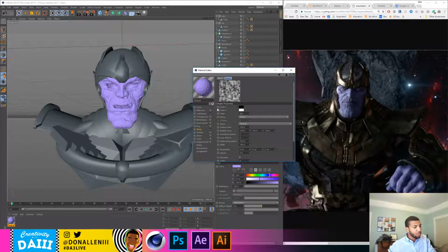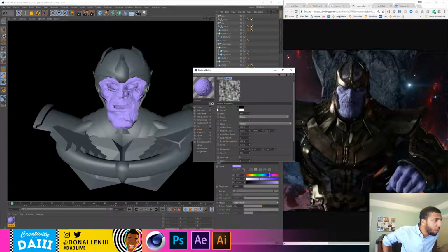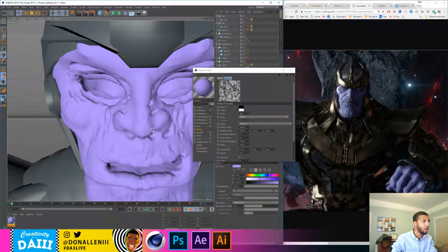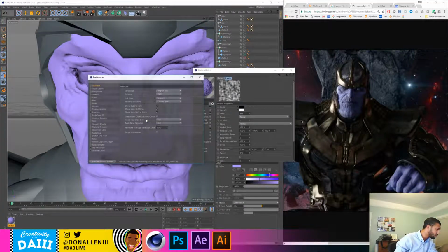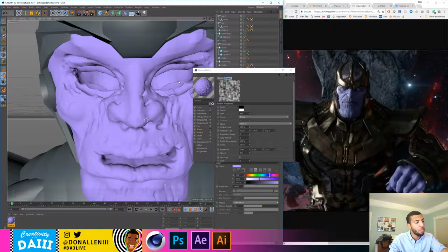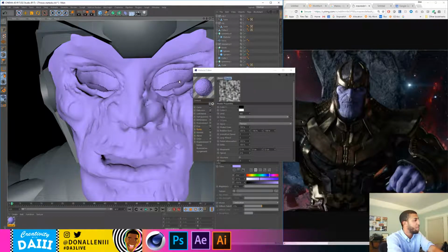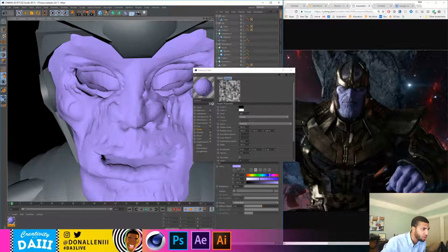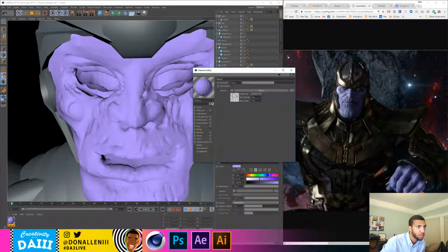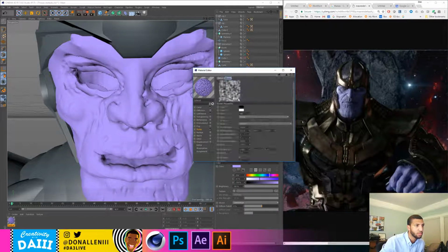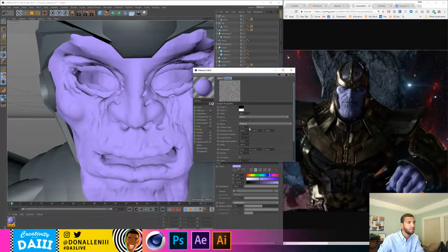So I added some bumps now, but this is the default bumps. You can barely see them, to be honest. I have to zoom in a lot, so I want to probably increase the resolution of the bumps so that it looks more bumpy. Gotta get bumpy. Yeah, I can barely see these bumps at all. So let's go ahead and go to our bumps, increase the strength of the bumps, go to the global scale of the bumps. Let's reduce the scale 98 to 45 to 11%.